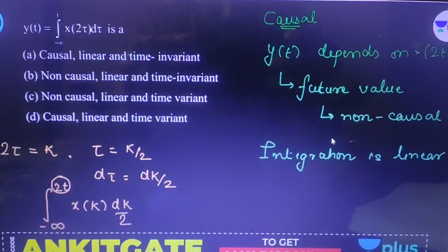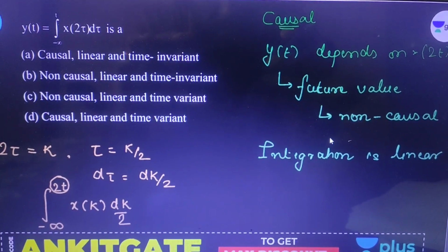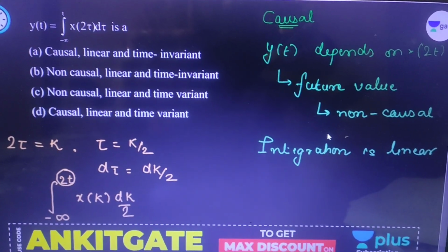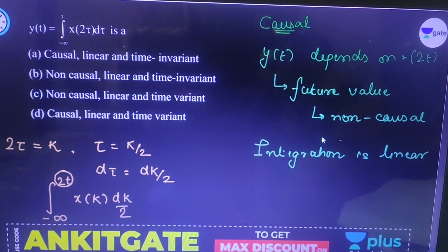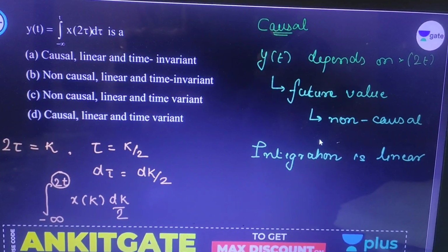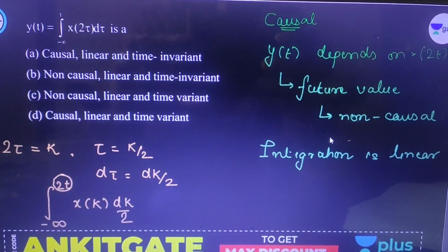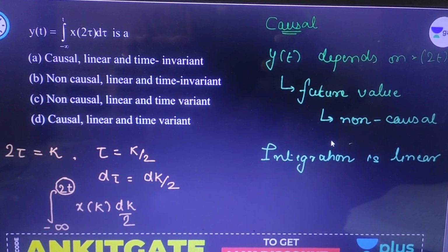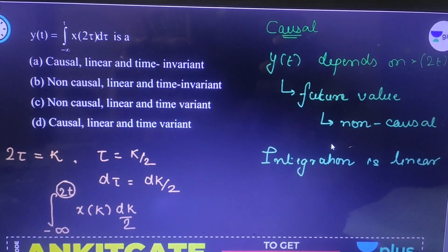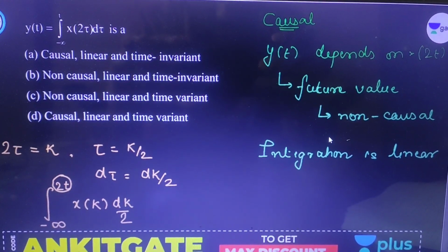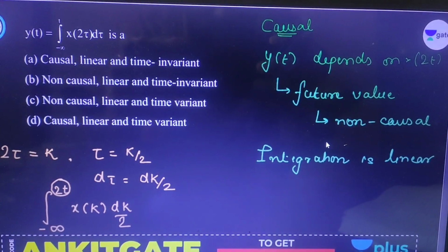Here he is asking about the causality, linearity and time invariance. As the output depends upon the future values, it is non-causal, and integration, which is nothing but sum, and differentiation, which is nothing but difference, these are linear.